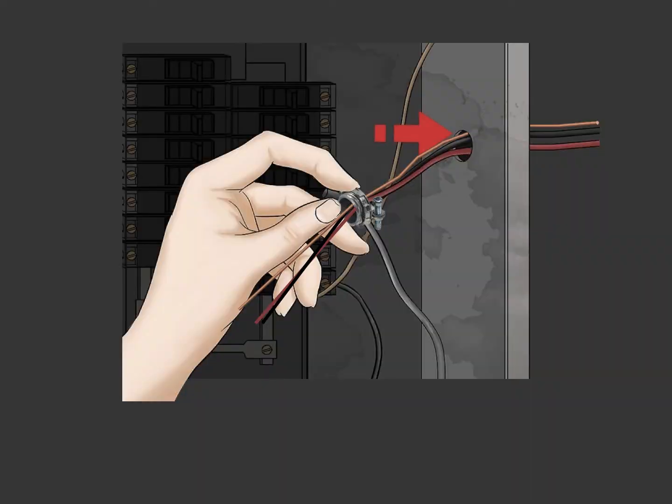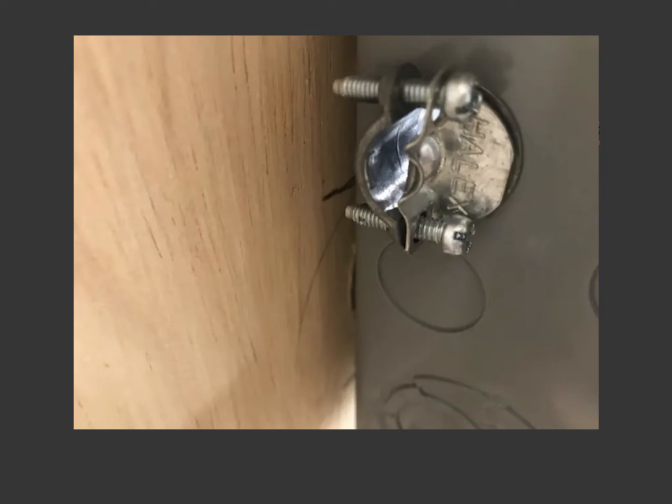Depending on the size and gauge of the wire, a knockout bushing must be used when stringing the wire through the panel side. This bushing, for number 14-3 wire and number 14-2 wire, is usually half an inch, but the knockouts and bushings could be as big as 3/4 of an inch. The bushing not only protects the wire from the sharp edges of the panel box, but it also locks the cable and wires in place.